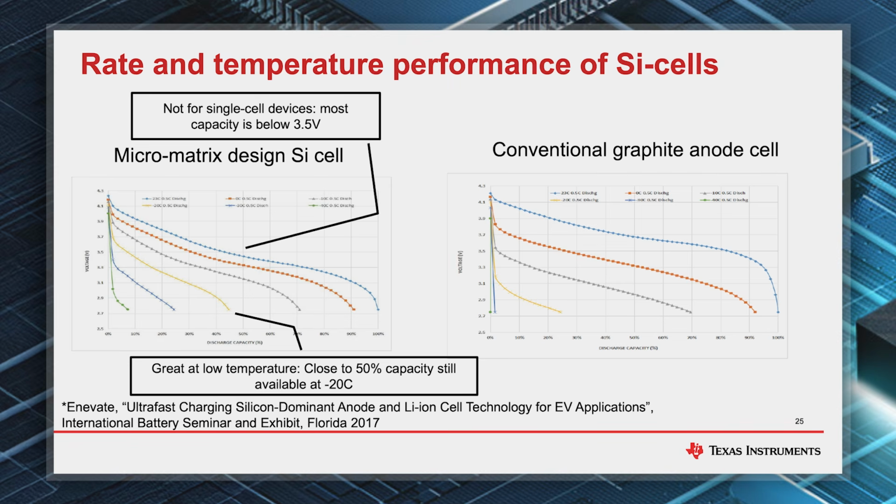So you know that with a traditional graphite anode, the diffusion rate of lithium into solid graphite becomes extremely low at low temperature. And so that is why this lithium plating that I was talking about starts at basically right at 0C. So both for charging and discharging as well, you have very big kinetic limitations at low temperature.